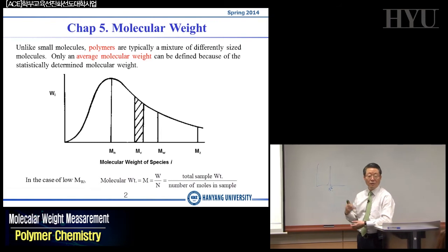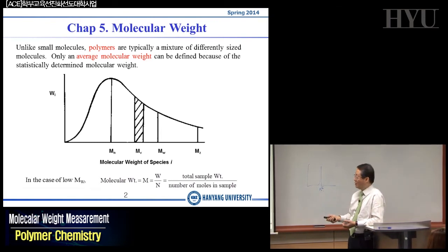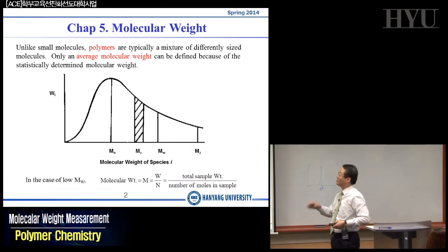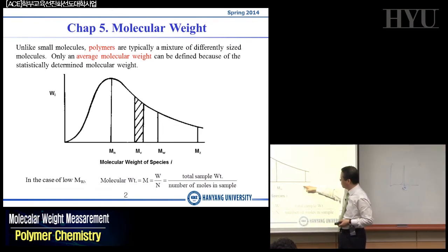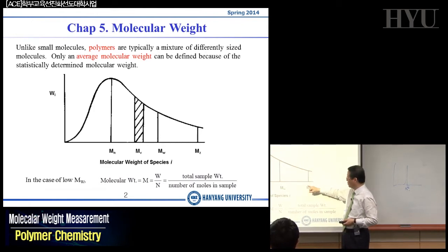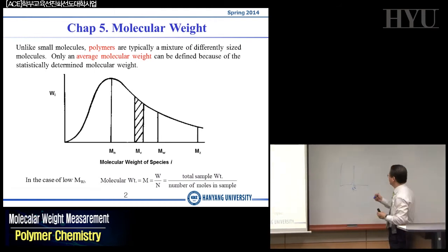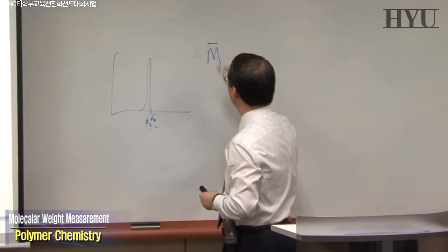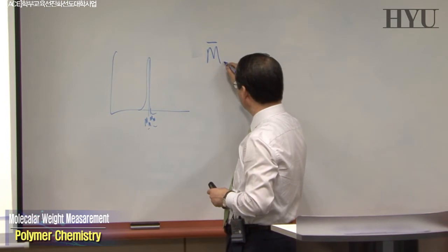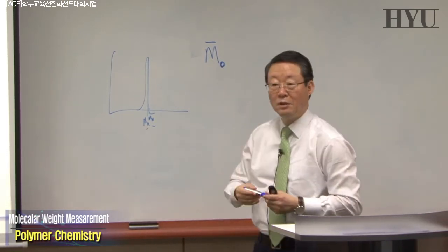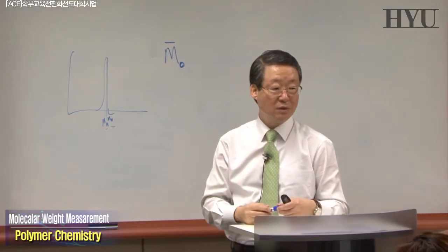The same analogy can be applied to polymers in this case, but we have to know how we can average these molecules, by number, or by viscosity, or by weight, or by some method called Z. So we have 4 ways of measuring the average molecular weights. If you put the average, then we always put a line on top of it. Okay, I just made a mistake here, but you just put the bar here, indicating the average. M bar is the average molecular weight, and the subscript indicates how you treat your molecular weight, I mean the average. Okay?